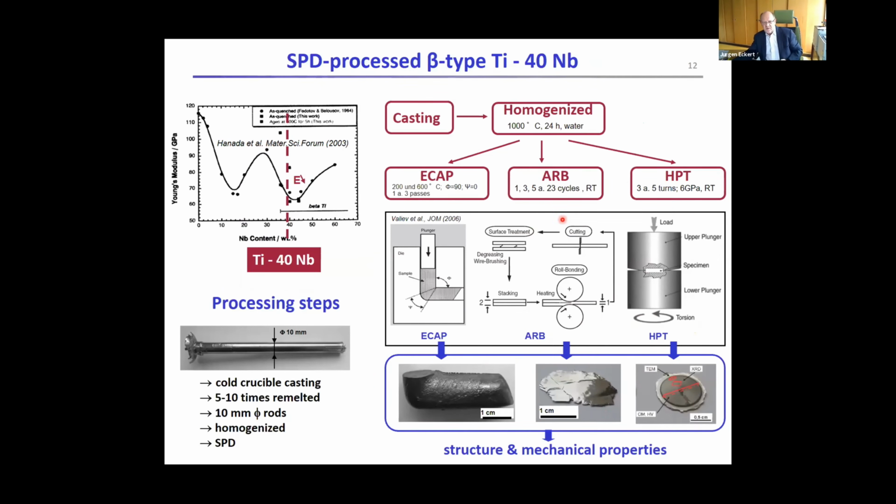You can also do it the other way. You can do it like the Russian colleagues usually try to do it, with a little bit more brutal deformation techniques, meaning methods that rely on severe plastic deformation. So for instance, like shown in the middle part here, you either take a rod and more or less extrude it around a 90-degree angle, or you do something like high pressure torsion on the right hand side, where you have a little plate that is put in between two anvils, where you apply a large pressure, and you basically also have a torsion deformation in there.